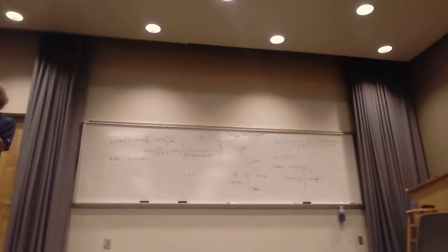It's the power the phone's receiving. And then it's divided by 10 to the minus third, and it's 10 times the log of that. And it will be, believe it or not, like minus 80 to minus 100 dBm, or dB milliwatts, pardon me. If you don't believe it, if you have a cell phone, get it out and play with it, you'll see this.